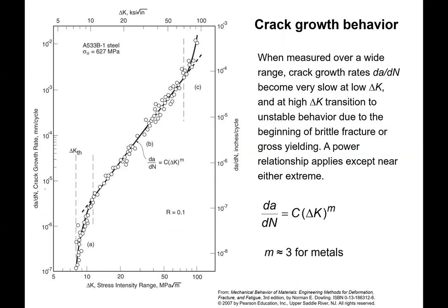We talked about this, I think, in the last video lecture. And then we're going to plot that versus the stress intensity, delta K, where through the experiment, we know what a is, the overall a, as well as this change in a.